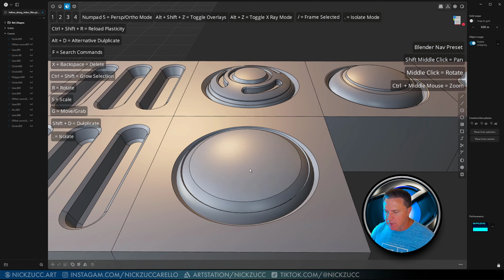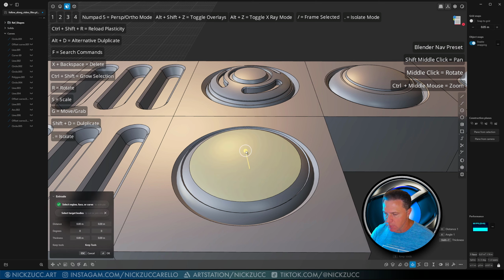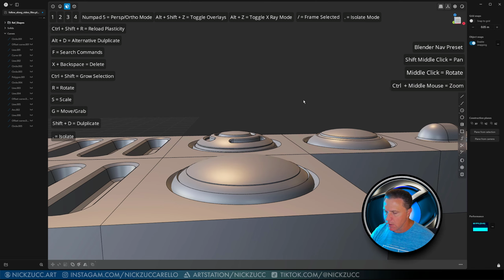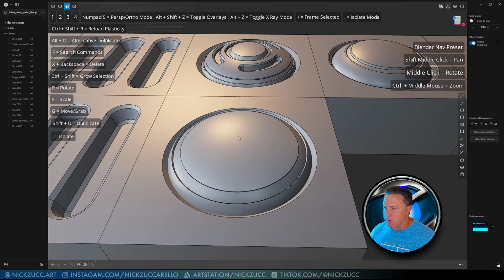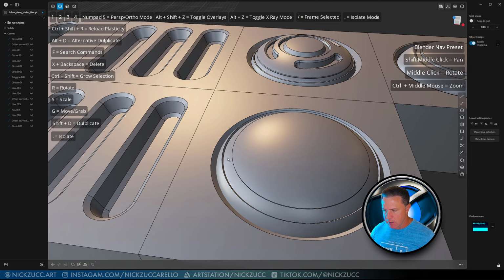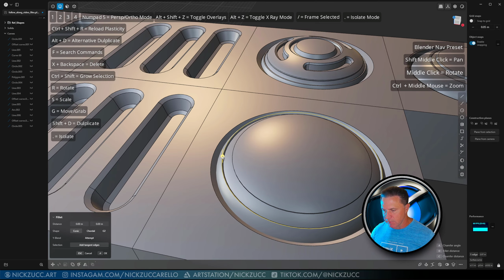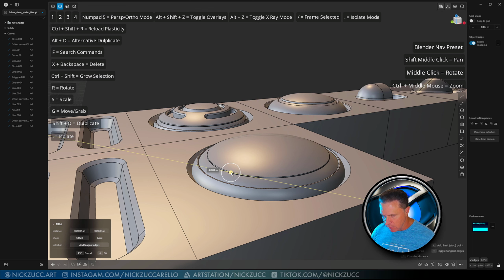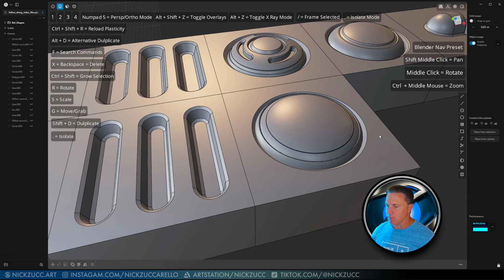Okay, so if I tap 3 on this, let's try to do extrude on this part like that, just to give a little bit of thickness here. So I'm just going to do a little bit, right click on there. So we've got that, and then we could select our edges here. So tap 2, and if I select this and hold down Shift and select that, we can give a little tiny chamfer or fillet on that particular part and piece.